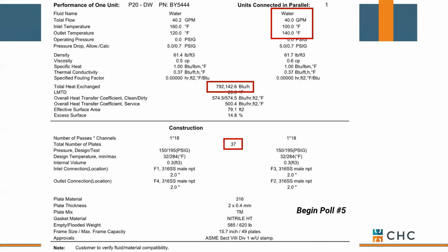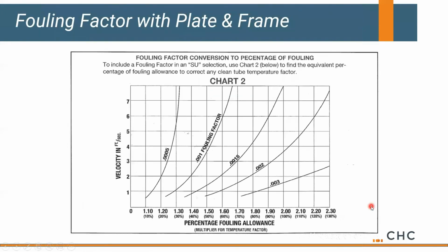Okay, let me launch my next poll. Let's talk about fouling factor with a plate and frame. This is a bit of a hot topic. Everybody who's used to sizing shell and tube is used to applying a fouling factor. It's just what you do. So when you go from a shell and tube into a plate and frame, you take that same mindset with you, and that is, let's apply a fouling factor. Let's talk about this.